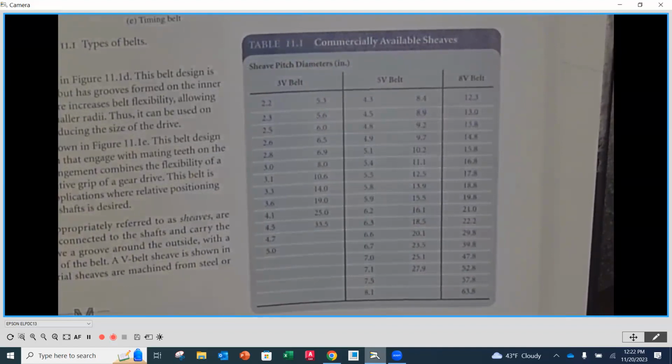If something is different for a manufacturer, you want to always be looking to their process for incorporating into your design, so that if there is a warranty issue that you need to go back to them for, they're going to ask you, how did you size it? How did you put it in? Did you use our recommendations? And then you'll have to prove that, for instance. And so you want to always be looking to their process, even though this is a good guide and these are going to hit the high points. A certain manufacturer might have some nuances that they want to be sure that you do as you incorporate.